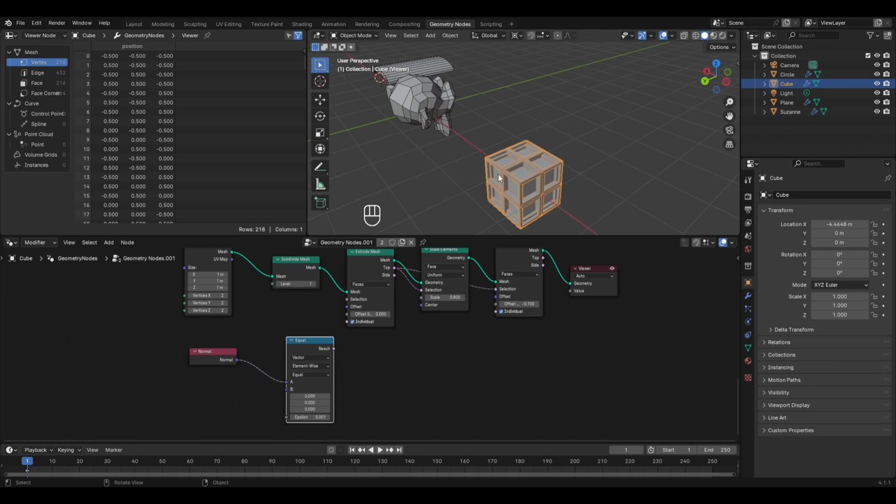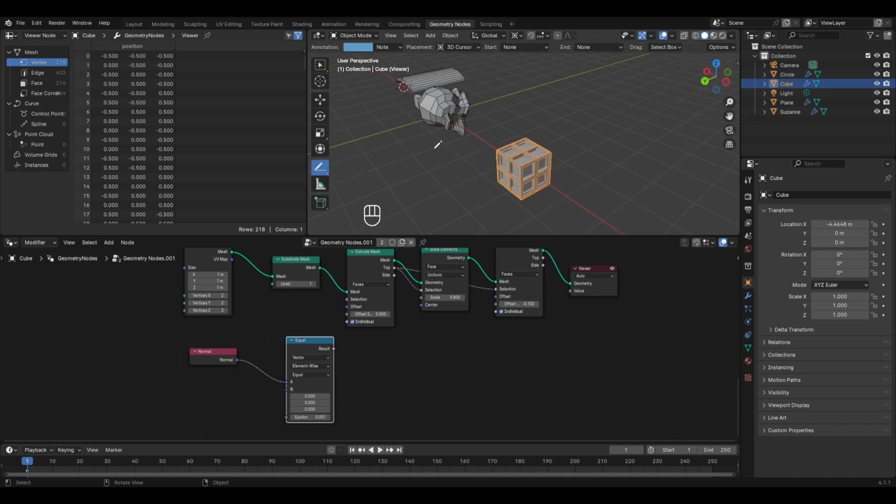For this you have to check the normal of these faces, and as I already told you, the normal will basically be the perpendicular line from these faces, and you can clearly see here that the perpendicular of these faces will lie in the y-axis like this. But another thing to check is whether this y-axis is positive or negative, and you can confirm it from here, where you can see that in this direction it is pointing the positive y direction, and if I take my cursor over here, then here you have the negative y-axis, meaning that this side is positive and the opposite side, that is this one, is the negative y-axis.